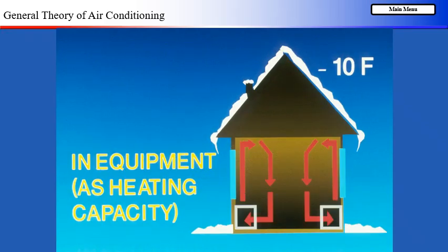Convection can also be at work as heating capacity when a baseboard heater is installed below a cold window. The less dense heated air moves upward, taking heating capacity to the load at the window, wall, and ceiling. As the air molecules lose their heat energy, they become colder and more dense, falling toward the floor. Cold air moves into the heater to make up for the warm air moving up, which solves the downdraft and cold puddle problem.